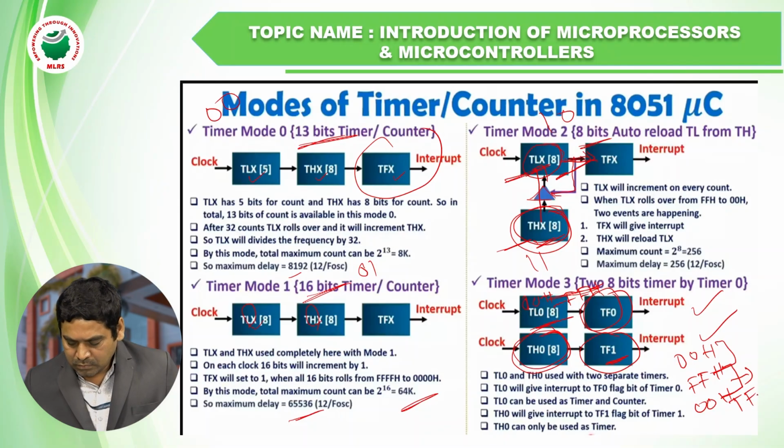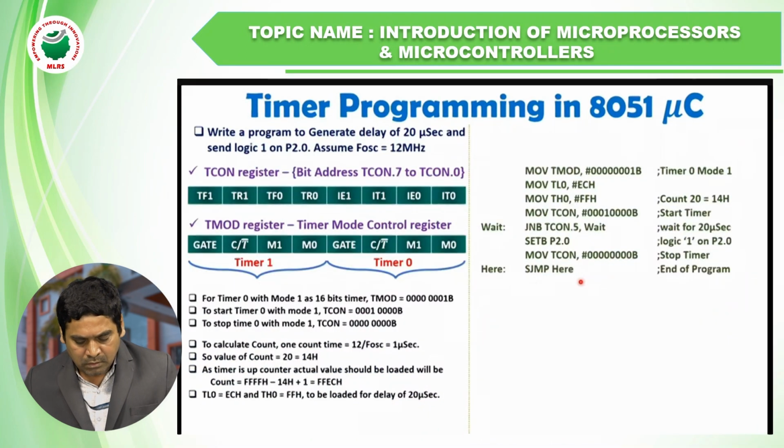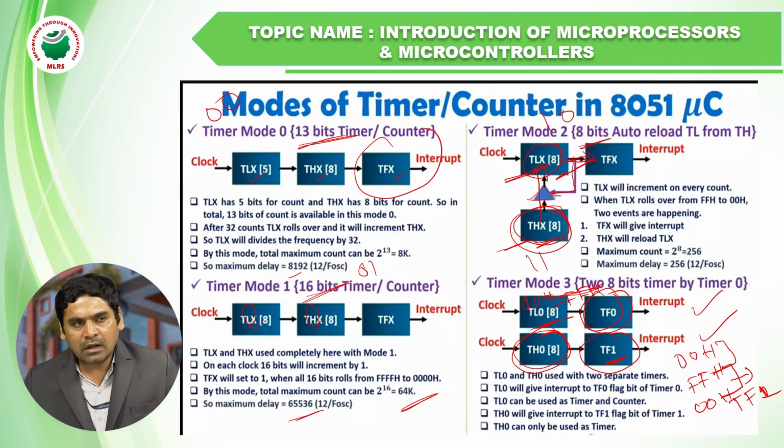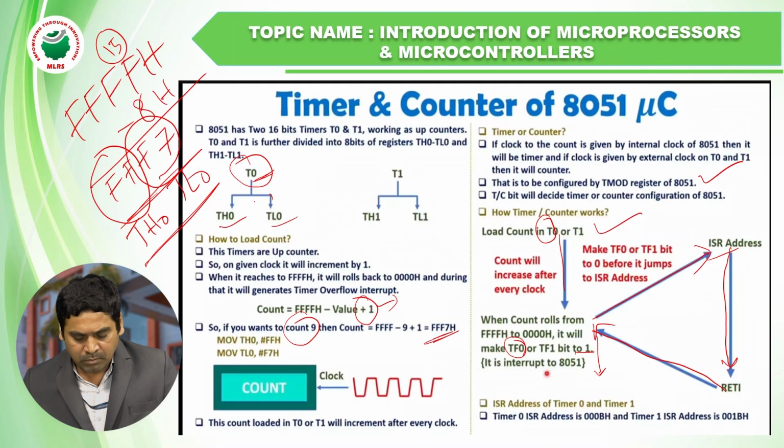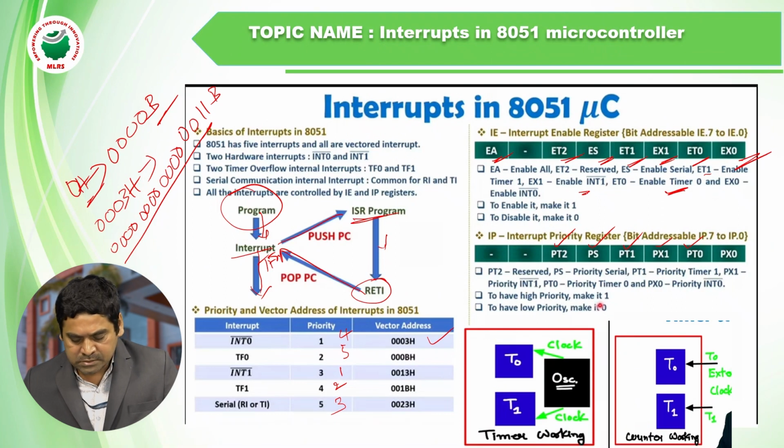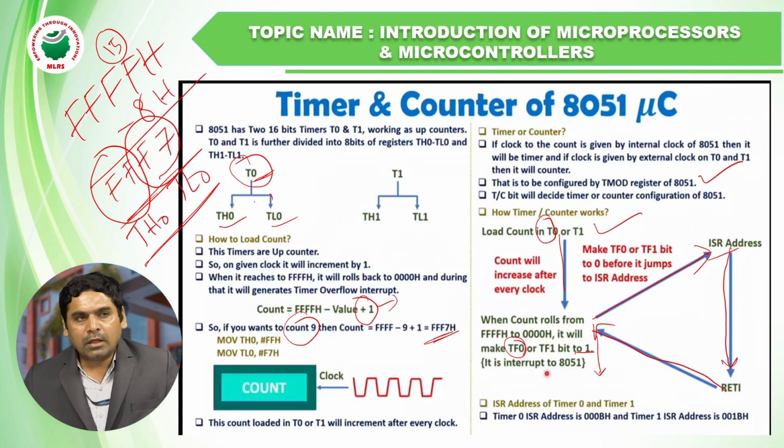of timer 0, TF1. So these all are about how timers and counters work: how they are divided into two registers TH0 and TL0, how the TMOD register selects the mode with M0 and M1, how the C/T bar pin and count start play the main role, the timer vector addresses and priorities, and how the T0 and T1 blocks work with the 8051's internal clock and external clock.